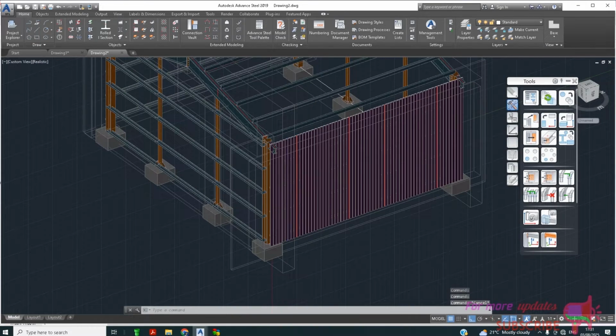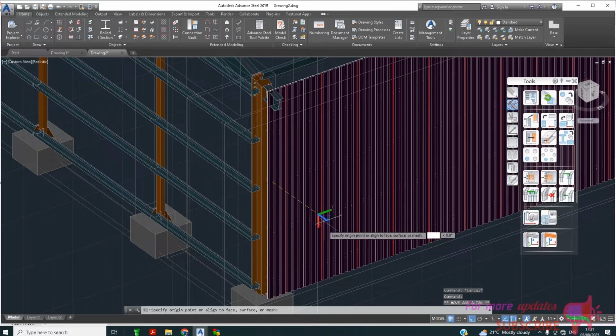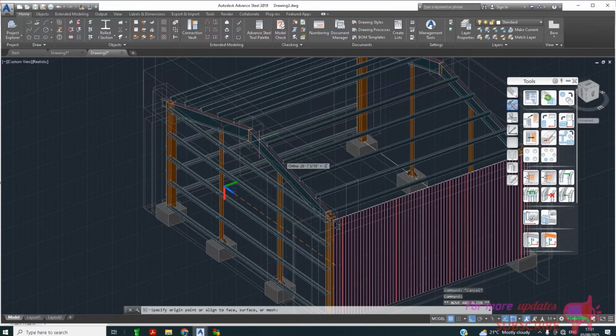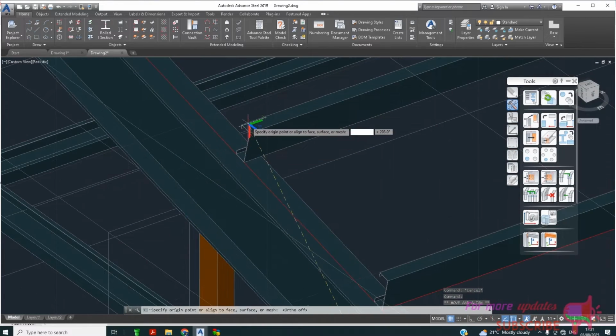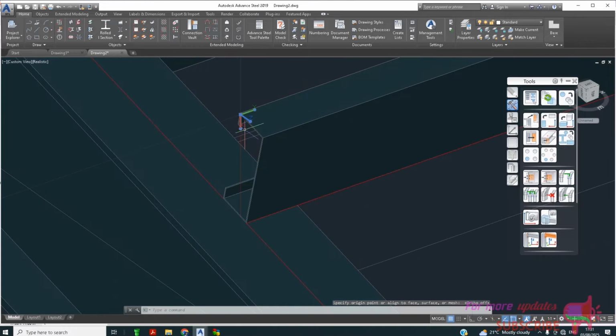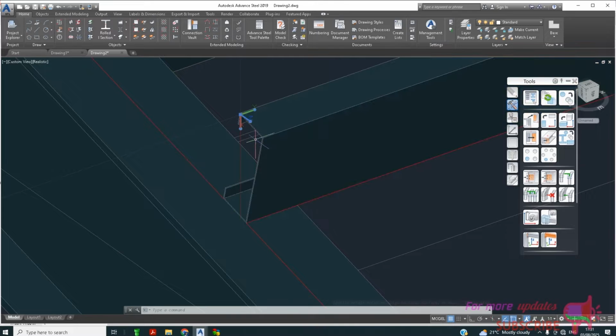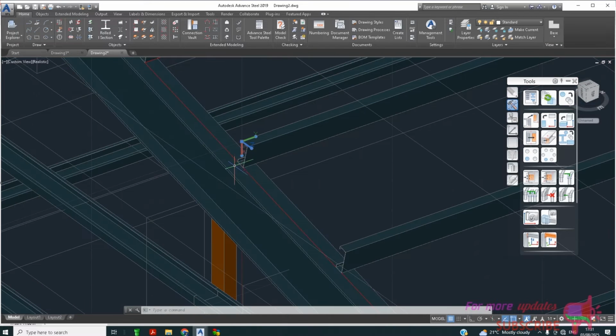The next, we're going to add the cladding at the top. I want to select my UCS. Just move it. I will uncheck here now because this one is not orthogonal. There's an angle here, so just do that, and then I want to rotate about y-axis so that the XY plane will be on that angle.